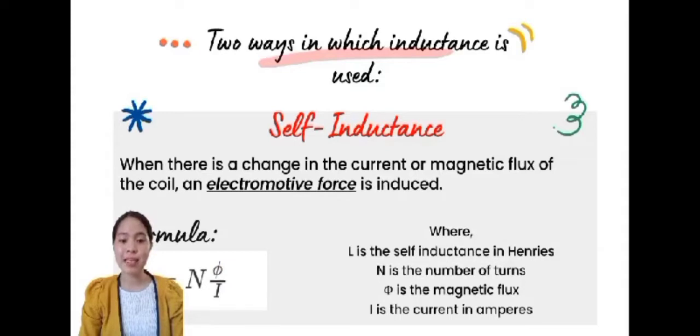When an AC passes through a solenoid, the magnetic flux linked with it changes. This flux change induces an EMF in the solenoid. This EMF opposes the EMF in the circuit. Due to this, the voltage in the circuit also decreases. So, the intensity of the bulb also decreases.